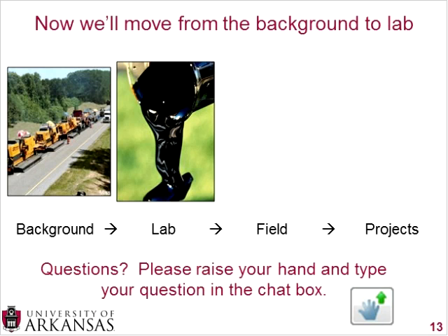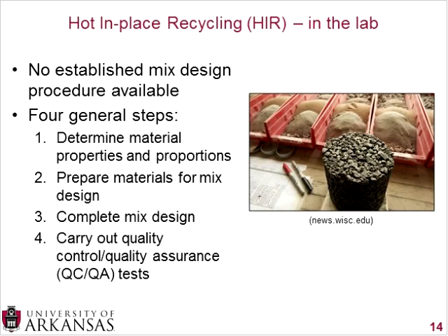All right, so moving into the lab portion of hot in-place recycling, there is no established mix design procedure available. So if you go out and you look at different state agencies and what they're doing, if you're looking at different contractors who have done HIR, there is really no commonly accepted HIR mix design procedure. But when you start looking at more and more of them, you will see that there are 4 general steps in the mix design procedures that are out there.